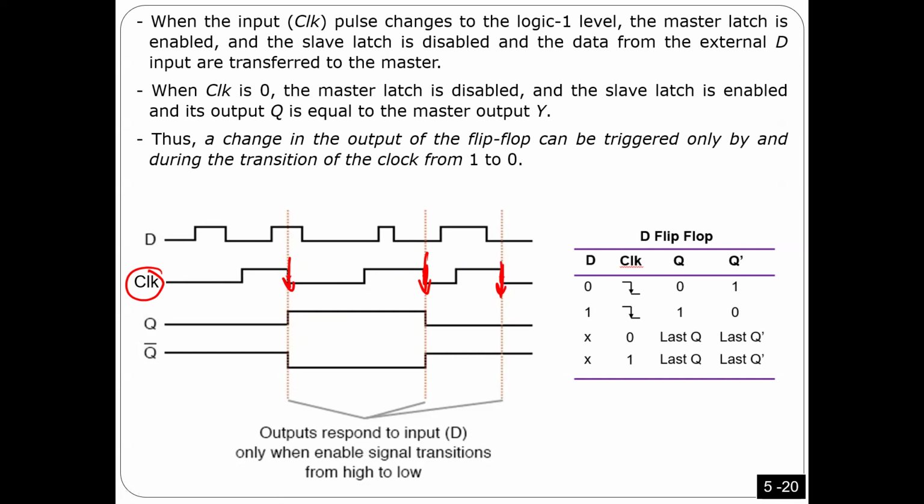If I tell you this is falling edge, you have to look at this moment, because the output is not going to change in the middle. So let's look at this exact moment. If we start, Q is 0, so it's going to continue as 0 until we hit the edge. At the edge, I need to decide whether it continues as 0 or not. Here, because this one is very easy, Q is equal to D. At this specific moment, D was 1. That's why Q has to be 1.